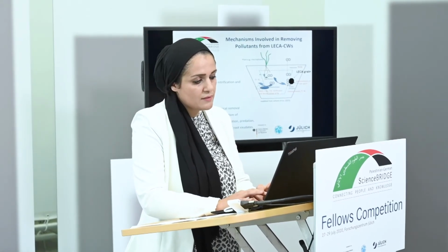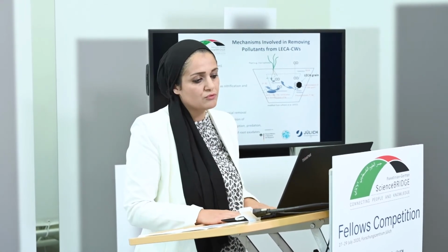So what are the mechanisms involved in removing pollutants in LECA-based constructed wetlands? There are many mechanisms, as I said, chemical, biological, and physical, but mainly for phosphorus and nitrogen, they are either absorbed or taken up by the plants, or degraded by organisms. The same goes for the organic matter.